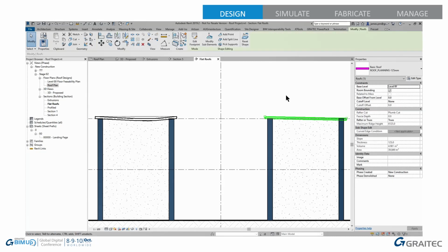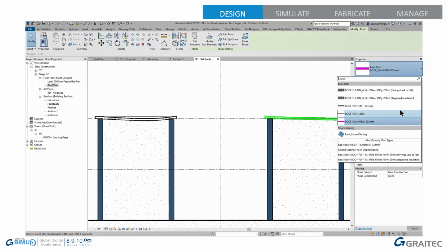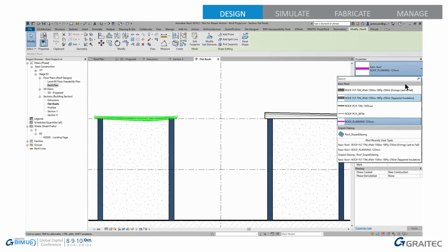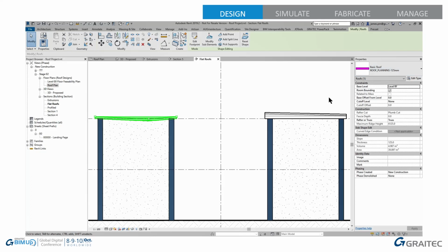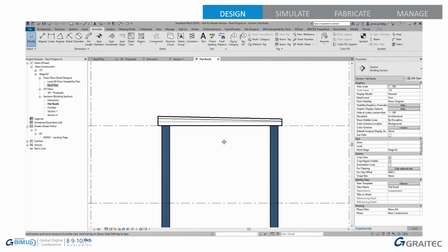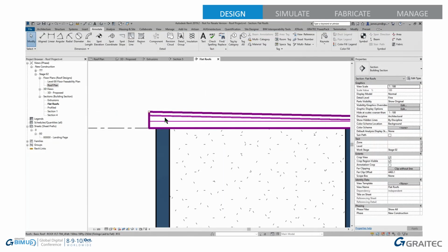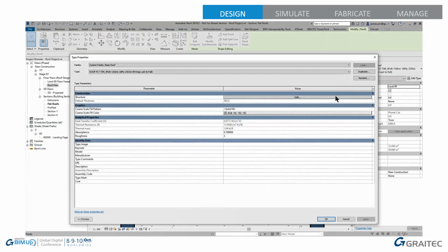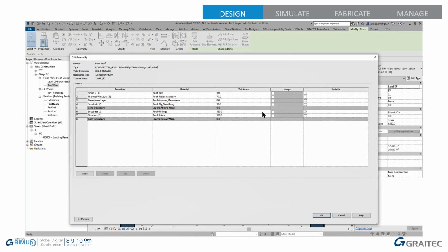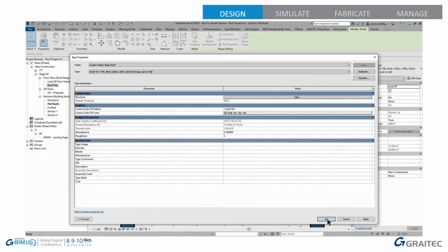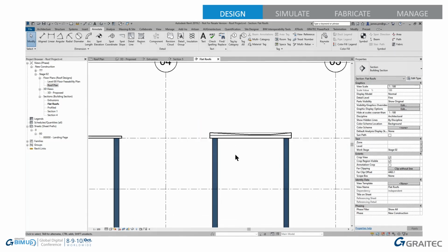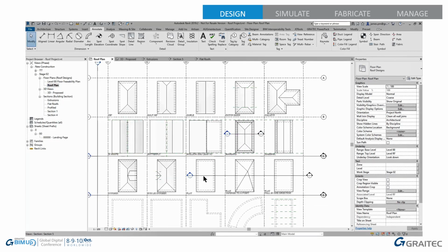So I'm going to show you a little technique on changing this. I've created some roofs in here beforehand. One of them is the roof with furrings, and this is a roof that has tapered insulation in here as well. Can you see how they've changed? With this one, the joists remain flat, and then the layer above it, called furrings, will filter down, so I mitre down. The reason it's done that is because I've made that layer variable. It's a really good technique for doing these roofs. And likewise, in the roof down to a point, I've done that with the insulation layer because we're using a firmer taper system.